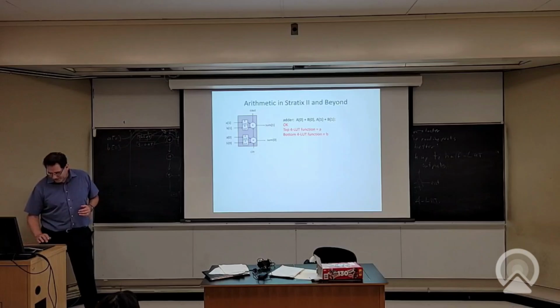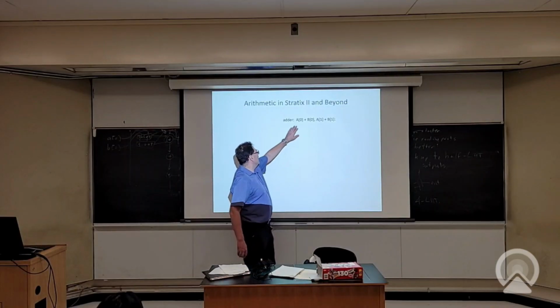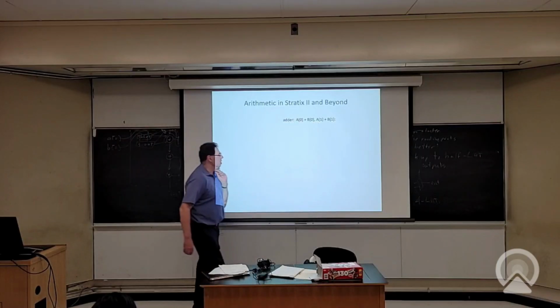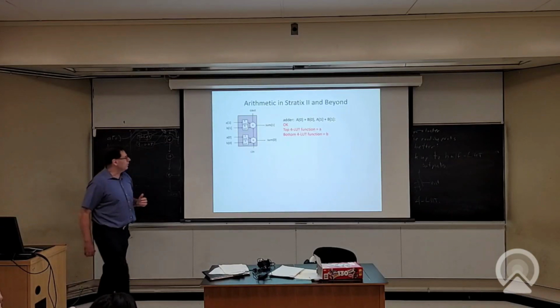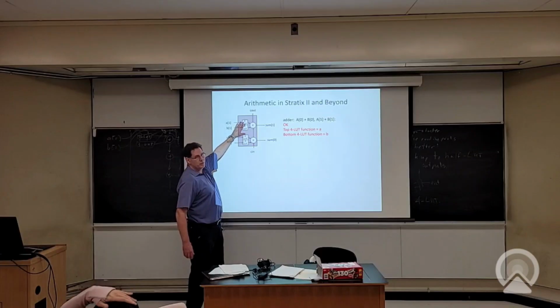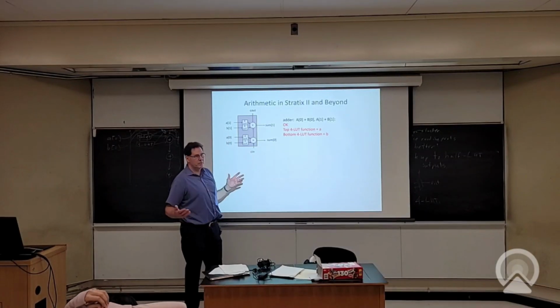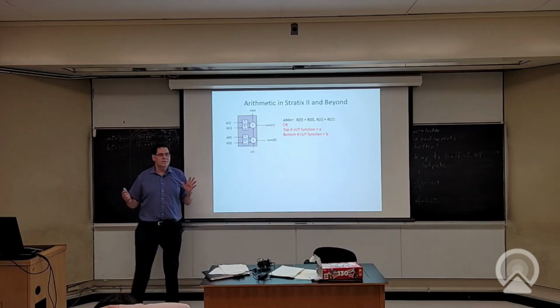Okay, so let's say I wanted to do this function. I wanted to do A0 plus B0, and the next bit would be A1 plus B1. So I just want to add 2 numbers. We already did that on the whiteboard. So we program this LUT to pass through A0, this to pass through B0, this to pass through A1, B1. So it's easy, right? These are 1 input functions, so we can program them in. And we only have 4 total inputs. The ALM can handle 8, right? So it's fine, okay? So clearly we can do addition.